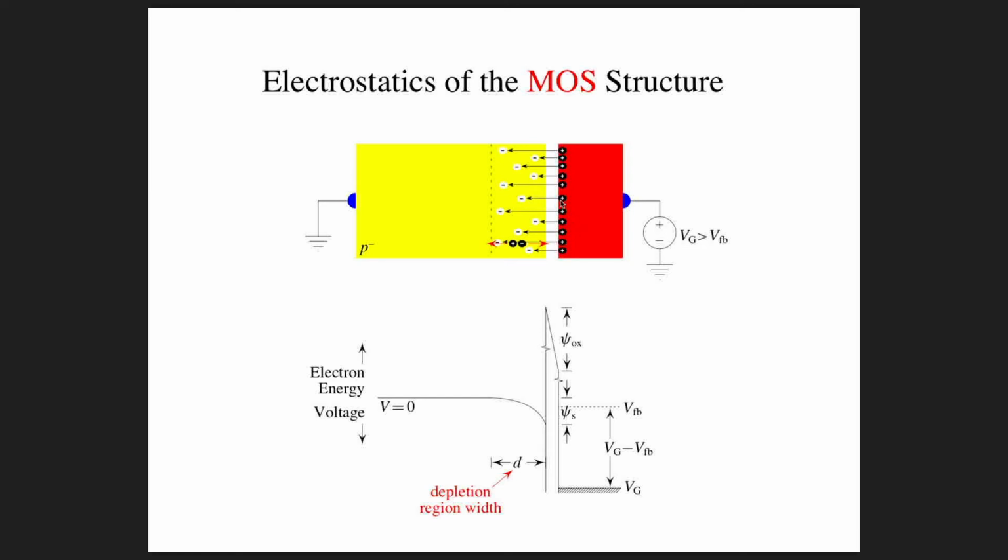And so what will happen is that this electron will hit this oxide. It literally runs into a glass ceiling. So normally this is oriented vertically, right? So that this silicon dioxide, which is basically glass, is oriented horizontally. And this electron basically zips up to the surface and hits that glass ceiling, and it sticks there. It just stays there, right at the surface.